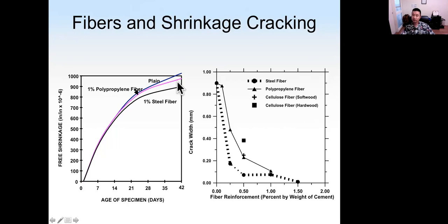And here shows how the fiber reinforcement percentage will affect the size of the crack. If we increase the percentage of the fibers, the size of the crack will be lower or even reduced to 0. And they use different types of fibers.